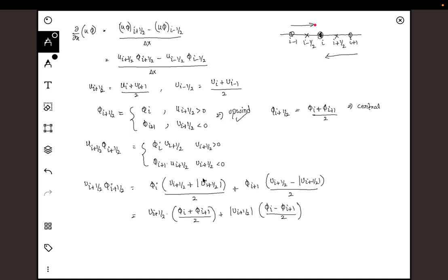So for example, if the flow is happening in this direction, and in order to estimate the value of temperature, for example, in this point, you are using temperature from the next cell. But physically, information is flowing from left to right. So taking it in this way is not physical. So taking an average of something that has no influence on this physically is not meaningful. But when we have weak advection terms and when diffusion is dominant, so when we have scenarios where the effect of advection is not very significant, then in those scenarios, information will flow in all the directions. Diffusion basically means it happens from all the directions.